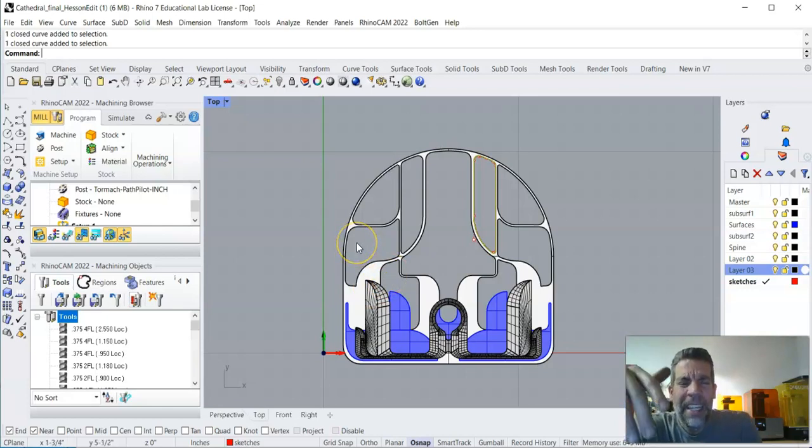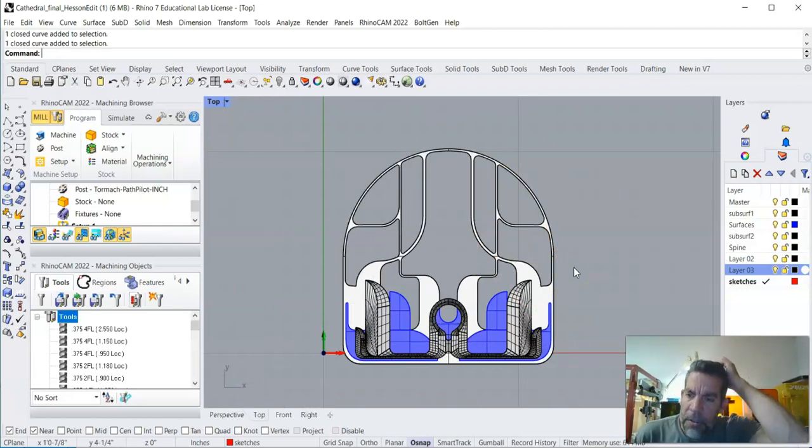So it's stuff like that, and RhinoCAM will alert you of those things if you are plugging that information in. I again usually don't worry about it. I usually use a lot of straight shank cutters, so I'm not using reduced cutters that have a larger shank. So again, I usually don't worry about loading those exact specs in necessarily.